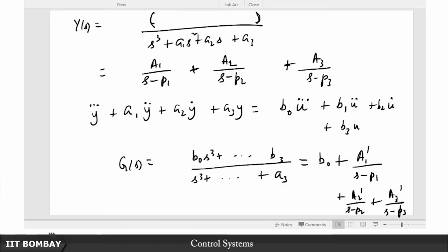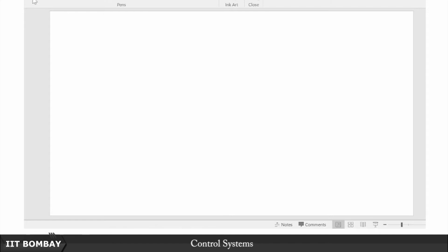Now, just before we go into a more practical realization of sorts, let me quickly touch upon another way. Of course, you can see that you can take the Laplace transform of this and get the transfer function corresponding to this system, but that is another way of looking at this. So, look at the initial premise that we had, right. So, we know that y of t is nothing but, if you take 0 minus to infinity, g of tau u of t minus tau d tau, right. We know this already for a fact.